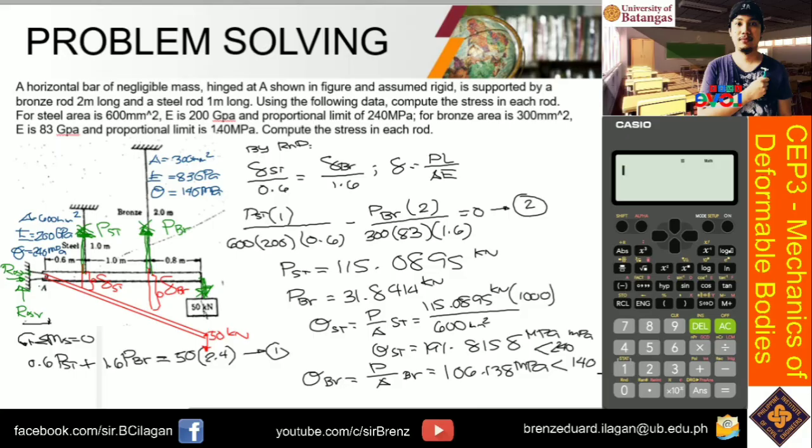Thus, making it less rigid. So, take note, it may be noted here that generally, the most rigid parts of an indeterminate structure carry the most load. This fundamental principle in the theory of indeterminate structures is known as the principle of rigidities.